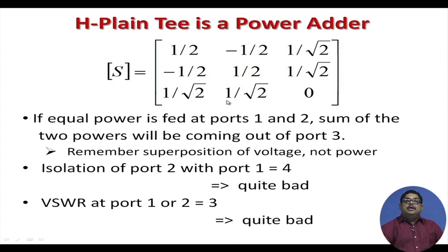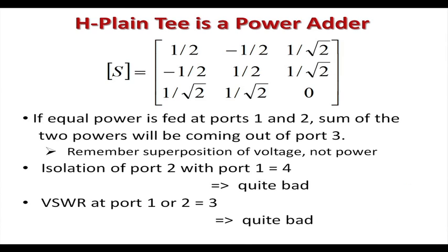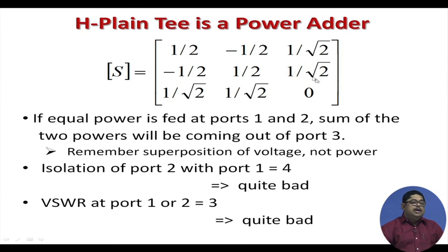So, it is a combiner. That means in H plane T, if I give port 1 and port 2 some power P1 and P2, P3 will be P1 plus P2. Again I am asking you to remember superposition of voltage, not power.